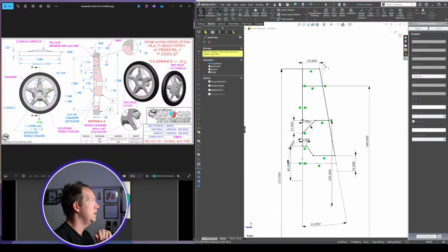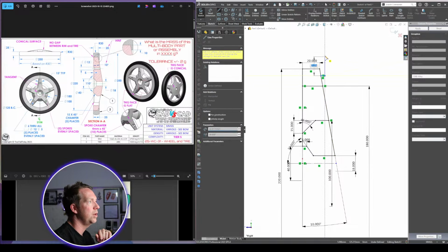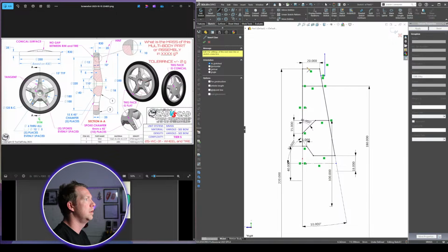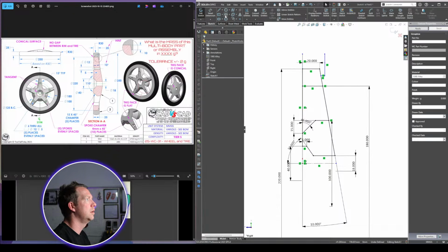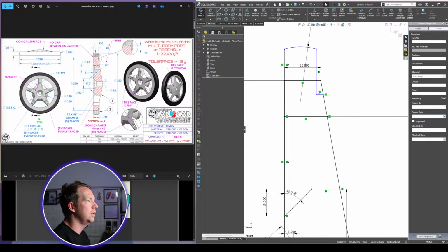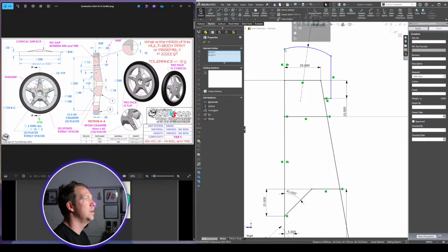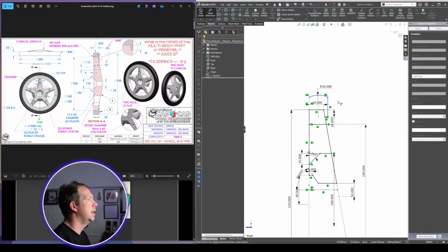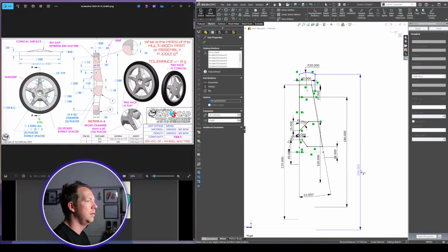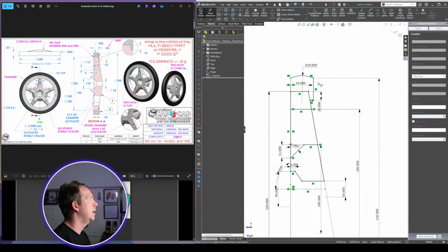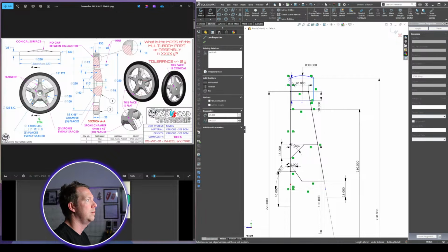Now the other thing that we can do in this, which I did do, is put in the next section. I actually drew another line up here, put in my arc, put in the dimensions for these, looking at stuff like the little 10 mil distance here, getting these 2 points horizontal, putting the 250 dimension in, and this element, the tire, has a width of 25 as well.